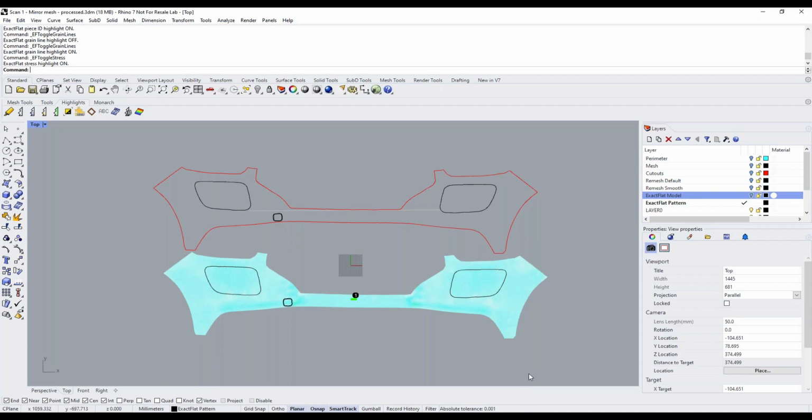Sure. When we use the global target strain, we have the option to apply either primary or principal, or transverse strain. I chose principal strain, which is in the direction of the grain line. So I essentially compressed the part from side to side when I applied that strain, and it's compressing that part of the pattern by about 2.5%.